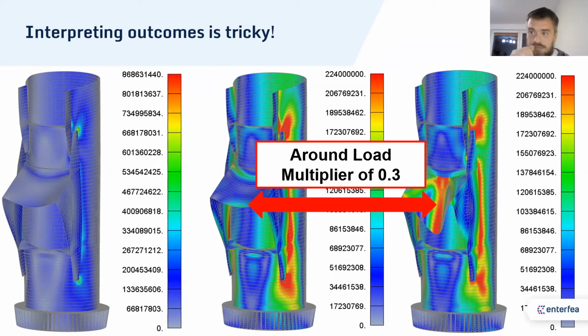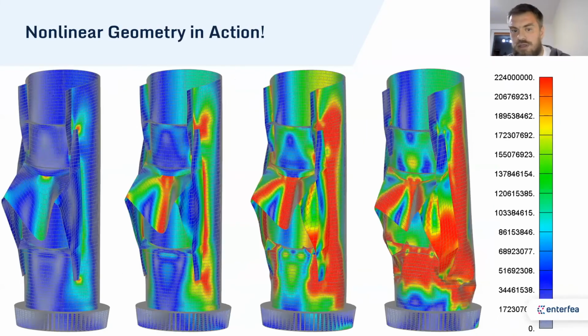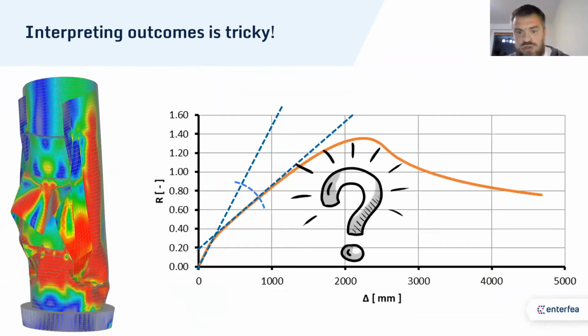And this can be surprising, of course, but you could actually predict it. It didn't cause the model to fail. It still functioned again, but it lost a certain portion of its rigidity. And this is what you can see here, this change in the curve with actually something secondary failing in our model. It didn't cause failure, but it changed how the model behaves.